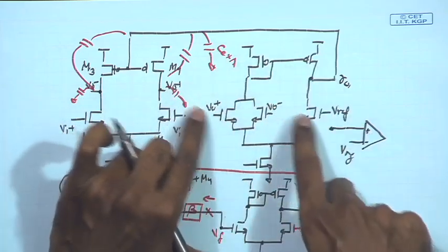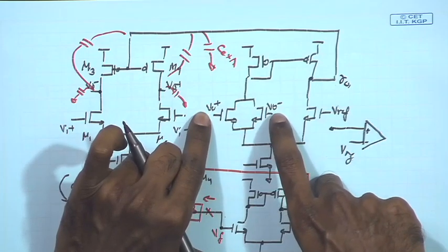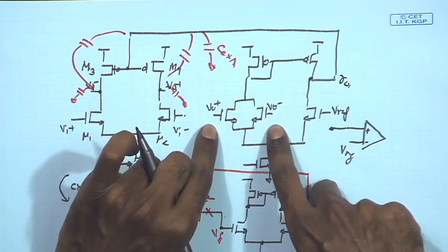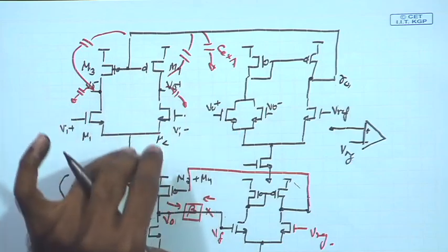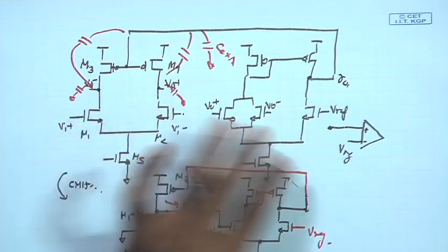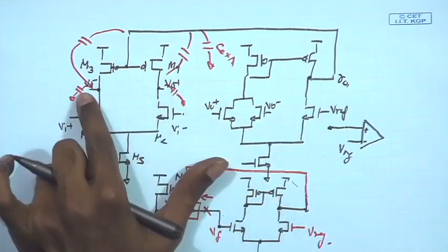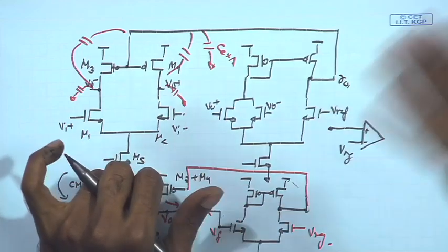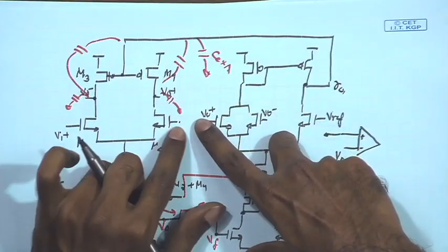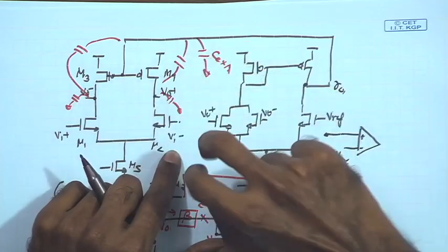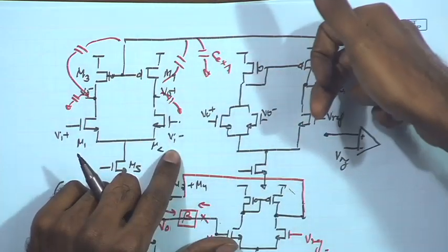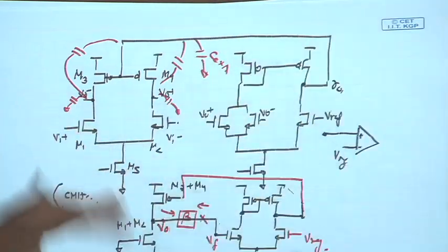So you have to make sure that of course that VGS drop is not too high such that the gate voltage over here becomes too low. So you have to make sure that the levels are consistent. You can use a buffer where you can have a common drain with NMOS and another common drain based on PMOS, and you can cancel the level shifts also.